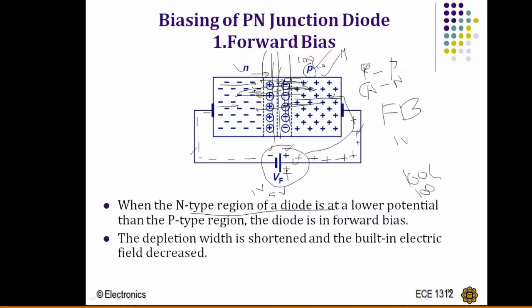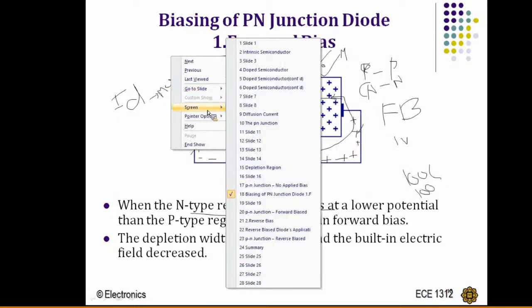The charge carriers moving from one side to the other constitute the current. That's why the maximum amount of current will flow in forward bias, because the maximum number of electrons can cross the junction and come to the p-type, constituting the current in the opposite direction, which we call the diode current. In case of forward bias, the diode current ID is maximum. Right. Now I will explain the same concept another way.